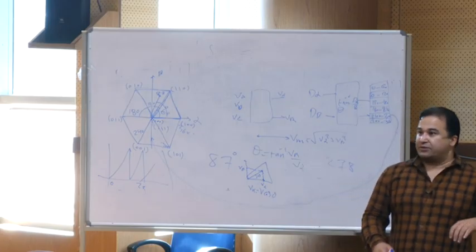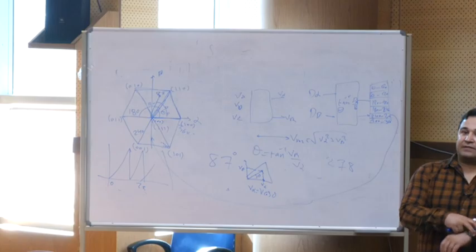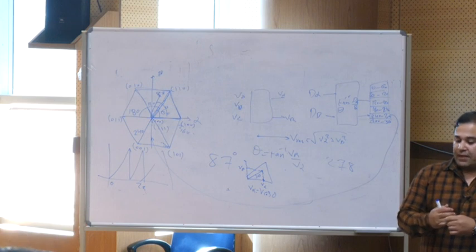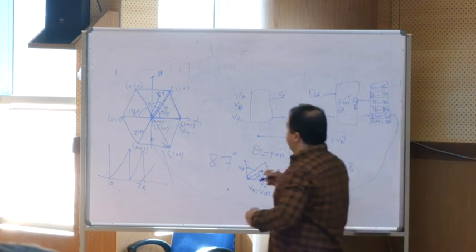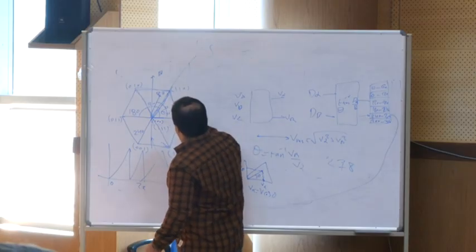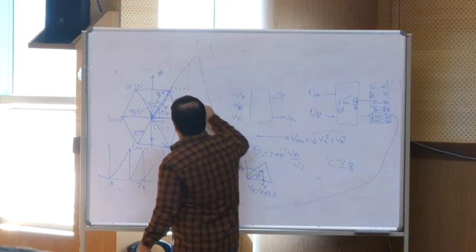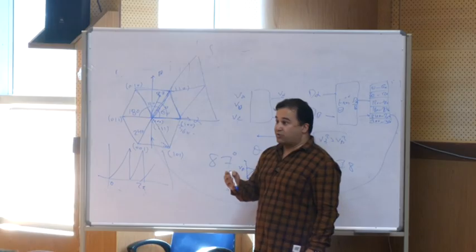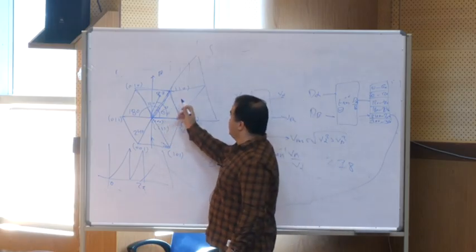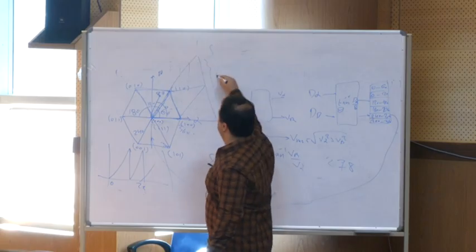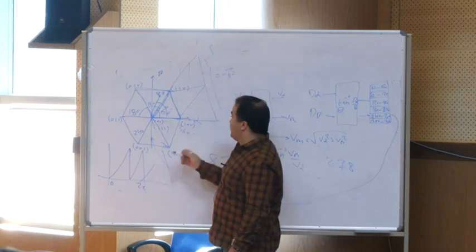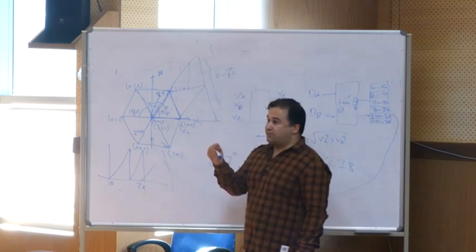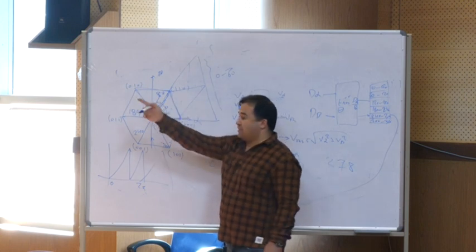I had a 3-level converter in my PhD, and for the 3-level converter, each sector goes like this. Because we had 4 transistors, in sector 1, between 0 and 60 degrees, we had states 1, 2, 3, 4, and each one also had 3 switching times. So for each sector,